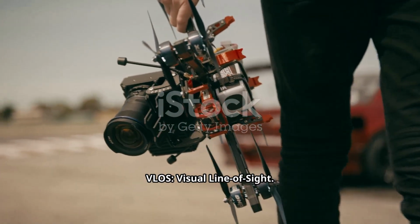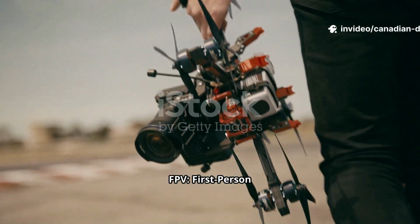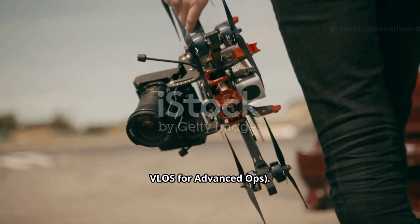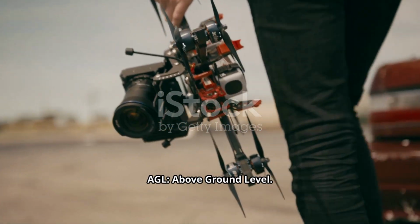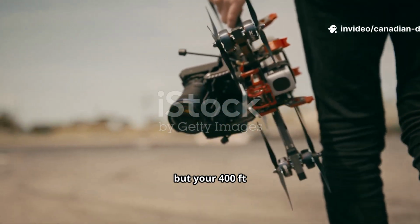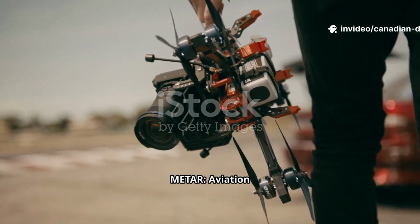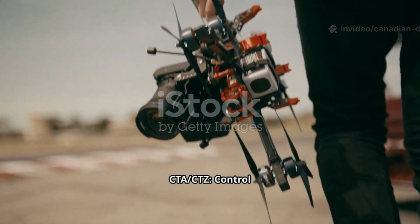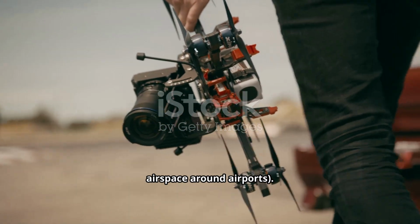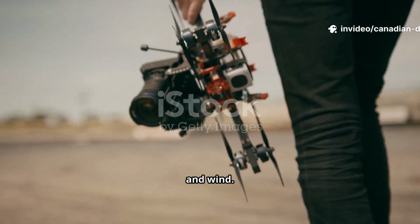VLOS, visual line of sight. BVLOS, beyond visual line of sight, illegal without a special permit. FPV, first-person view, using a video feed, but you must still have a visual observer maintaining VLOS for advanced ops. AGL, above ground level. MSL, mean sea level, used in aviation maps, but your 400 feet limit is AGL. NOTAM, notice to airmen. METAR, aviation routine weather report. CTA, CTZ, control area, control zone, types of controlled airspace around airports. Dynamic pressure, the pressure on the drone from moving through the air, affected by speed and wind.